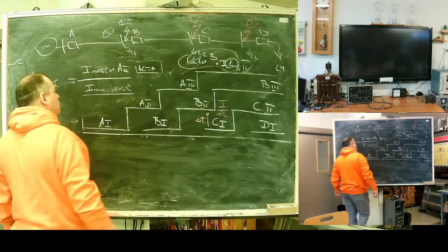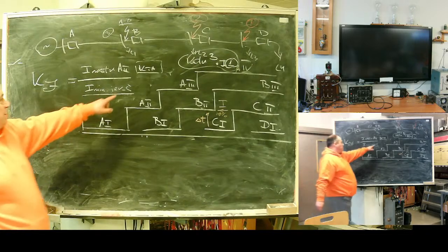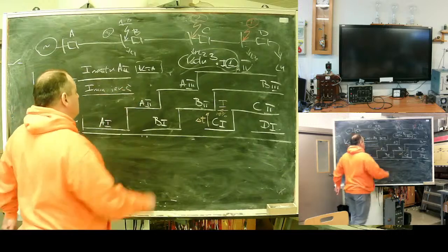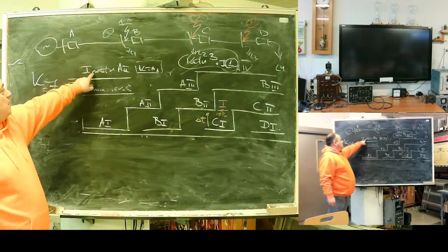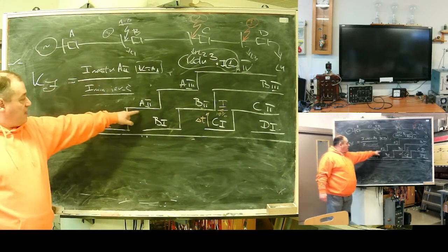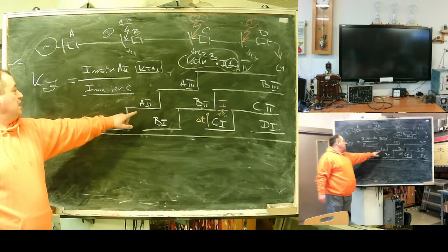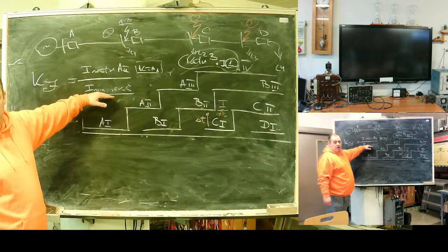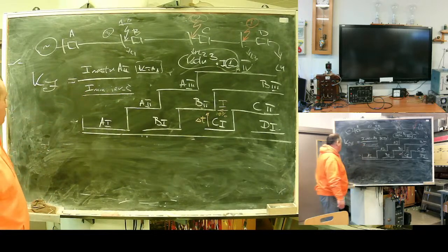Important: maybe needed, maybe not needed. Depends how you write, in primary amps or in secondary. If secondary, you need to place the transformer ratio here. Setting for your next zone protecting the end of line, divided by current of minimal internal fault.